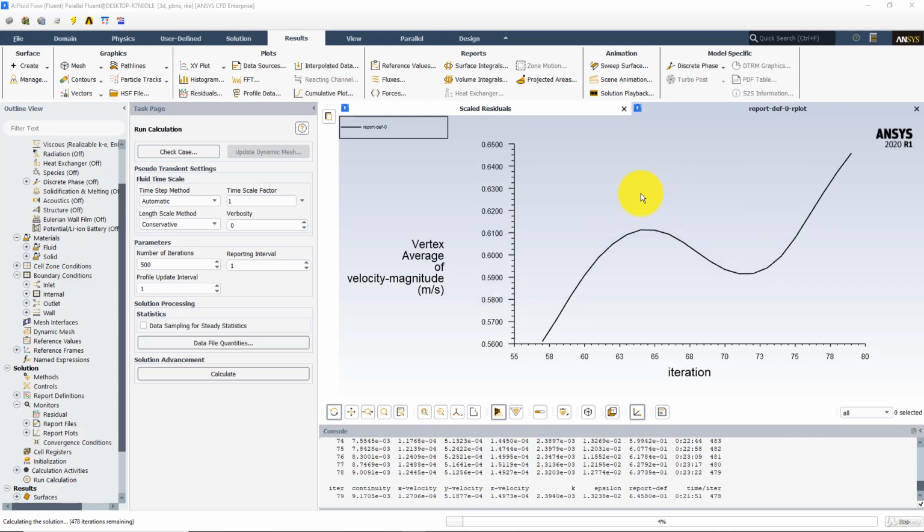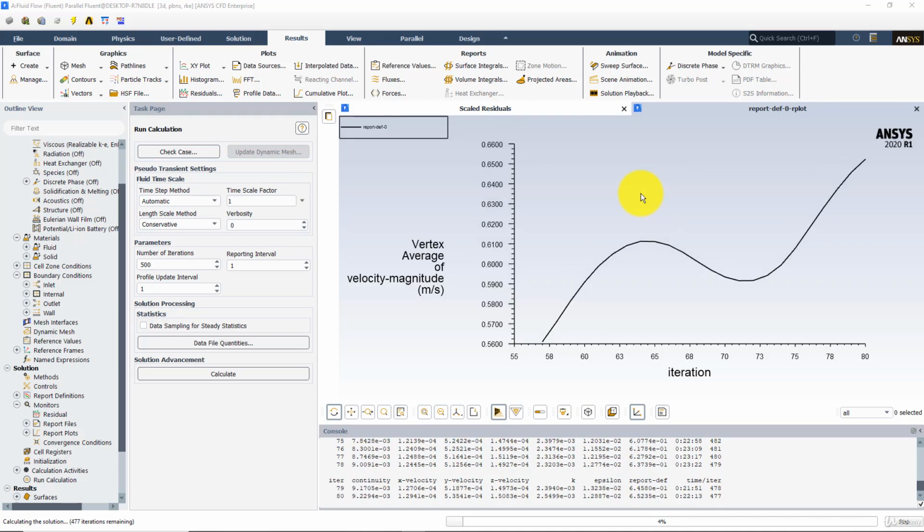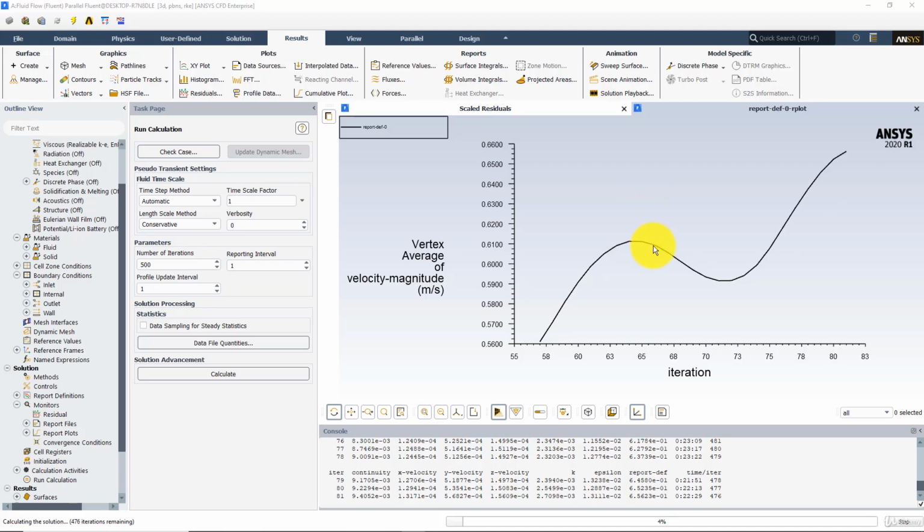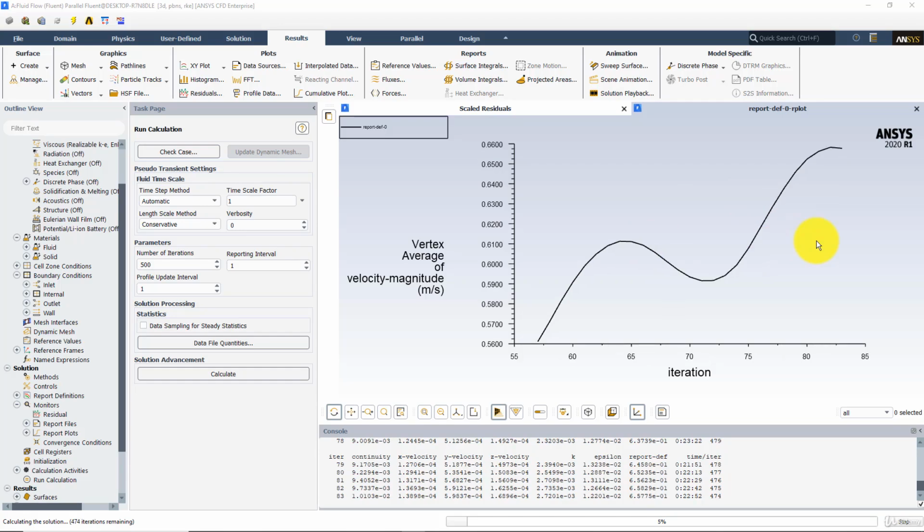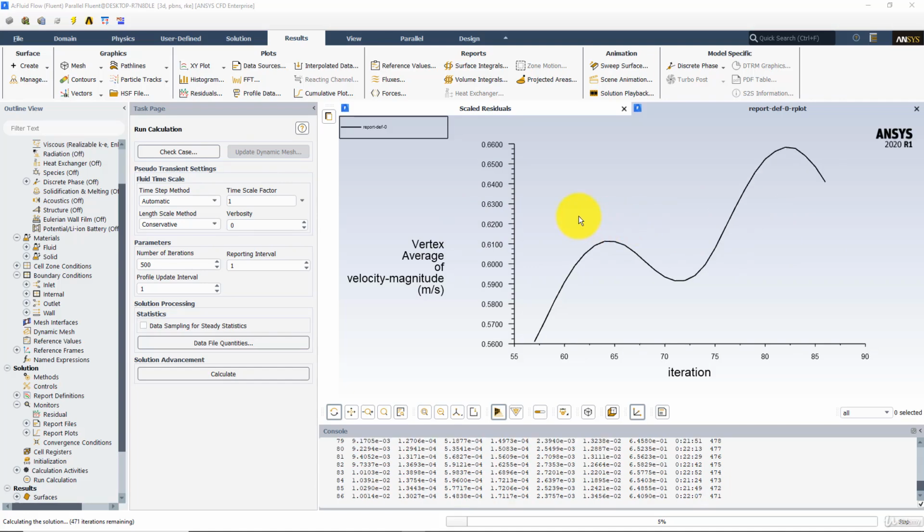That is when there is a separation bubble, which is obvious with the double contraction, and the U bend, not a U bend but a 90 degrees bend. So it's very obvious that the flow will become an unsteady or transient flow. In that case, we don't get convergence in a straight line. Rather, we get what is called periodic convergence, meaning the value will vary within some range, and then after some interval it will repeat itself.